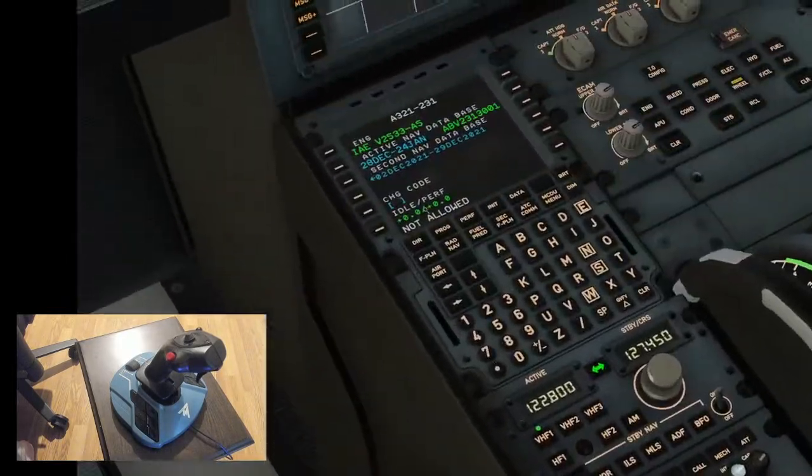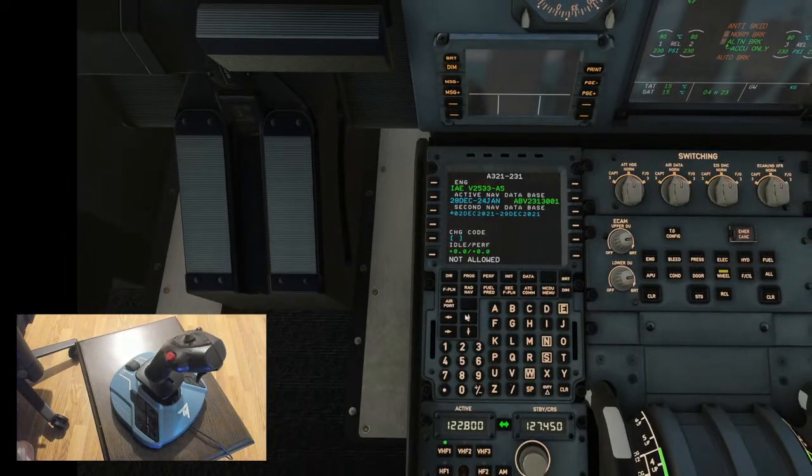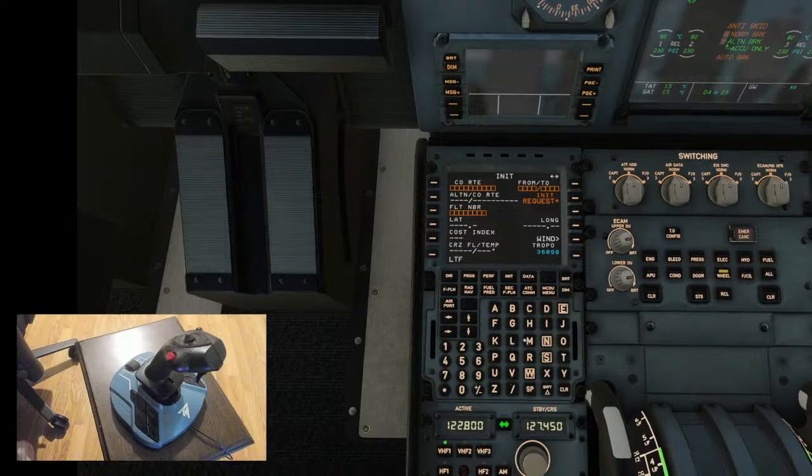Okay, from here I can start my flight planning. Here is the initialization page. At the moment the from-to page, LTFM, should be filled very properly. Start point will be LTAU and LTFM our arrival. Flight number TK3223. Cost index for Airbus that I choose is 12, and cruise flight, due to we are flying through the west,